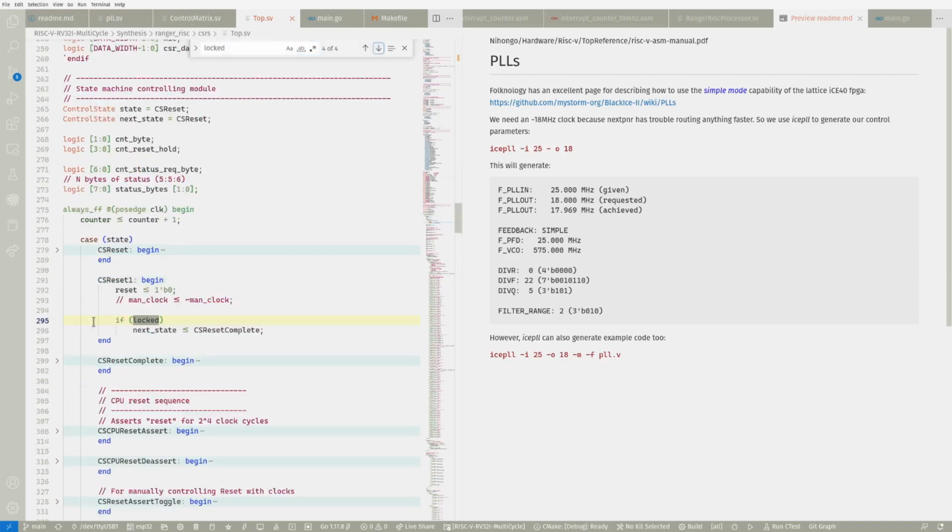We'll come into the reset, and we won't leave the reset until the PLL has locked on to the frequency that we want. It's pretty fast, and I highly recommend that you actually use the lock signal coming from the module, because your code may try to run before the signal has been locked, which can cause some really strange behavior from time to time.